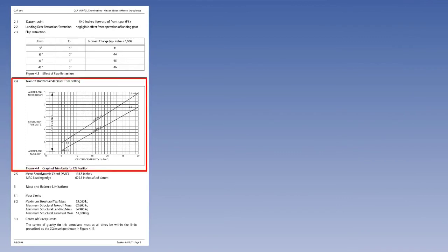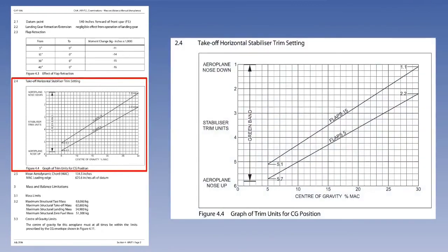If flap 15 degrees is the required flap setting for takeoff, then the trim unit for centre of gravity position table in CAP 696 must be used. This was covered in the introductory lesson on medium-range jet transport.